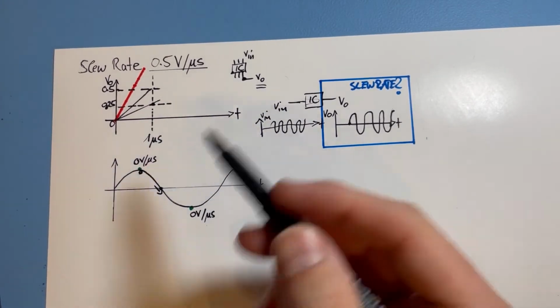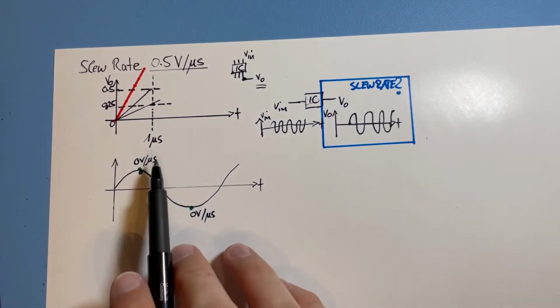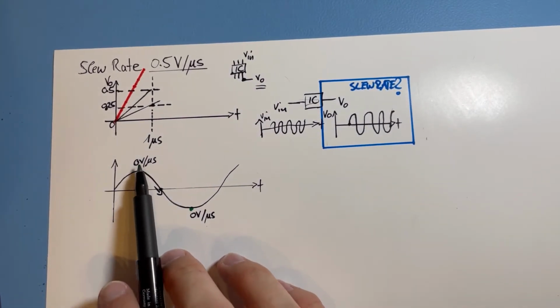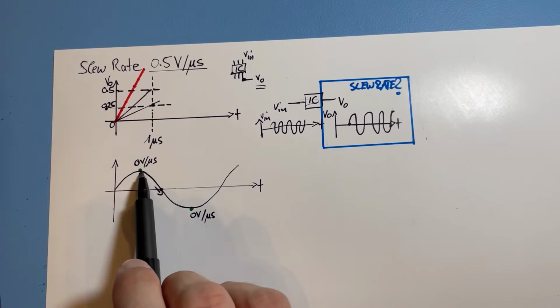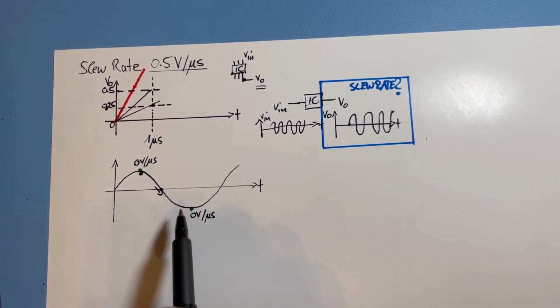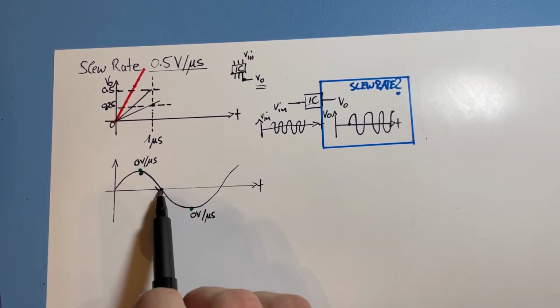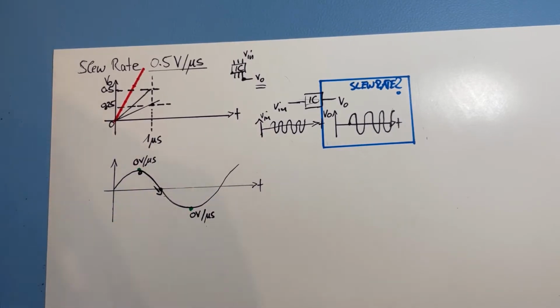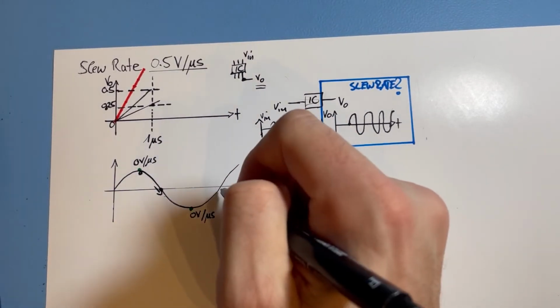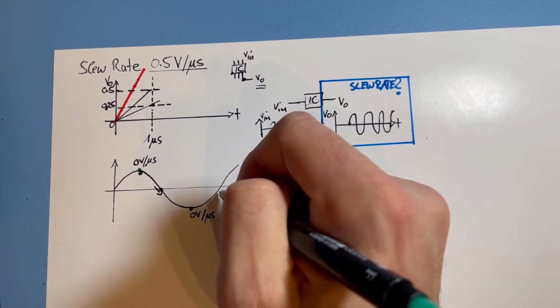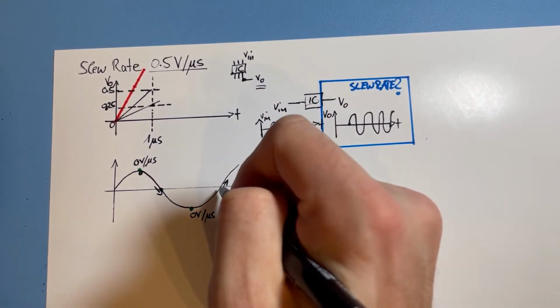It's a simple physical units recalculation. You can always express it in volts per microsecond. And at each of these points you have a change per microsecond in volts, and the biggest change you have is at this point. And also falling, and then rising also here at this point again.